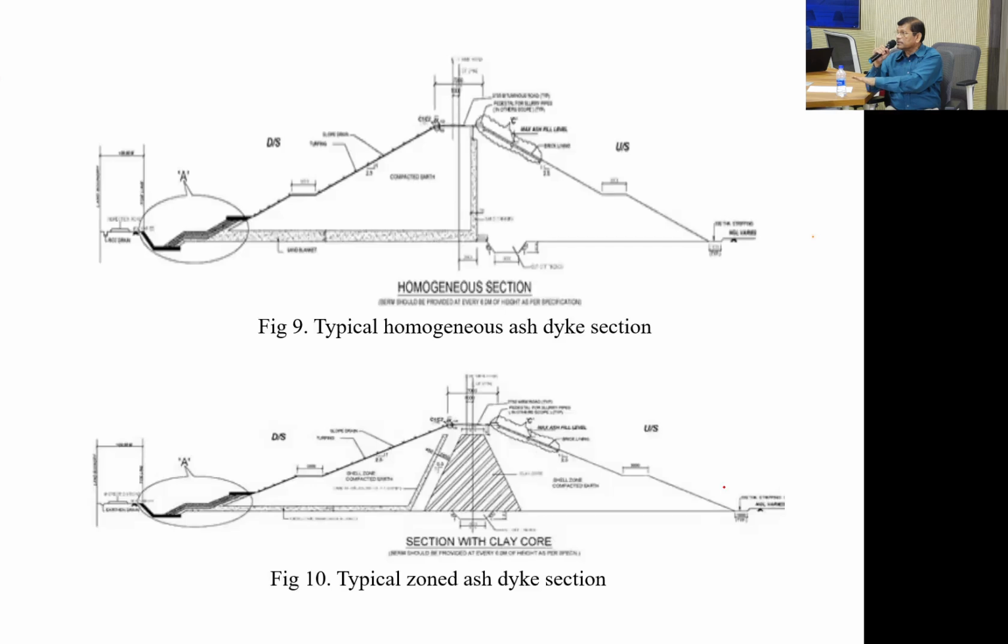That is one of the assumptions of the liner, that it is installed far into the ground, so that it is protecting. But if there is a gap between the two, then what are you doing? That's why anything steeper than a 3-to-1 slope is very difficult to line. Practically it is very difficult.